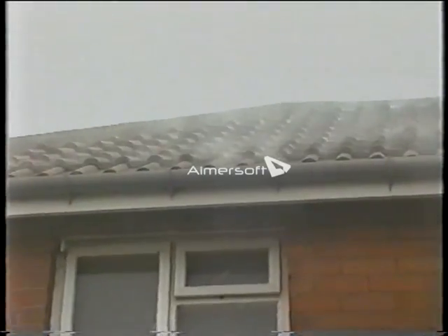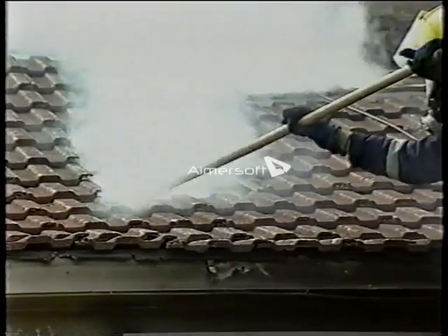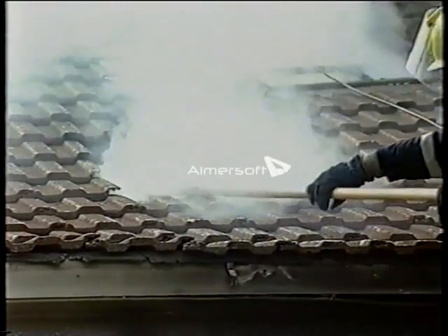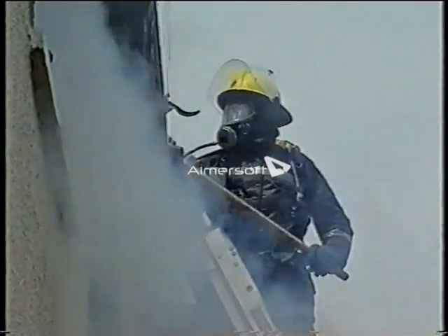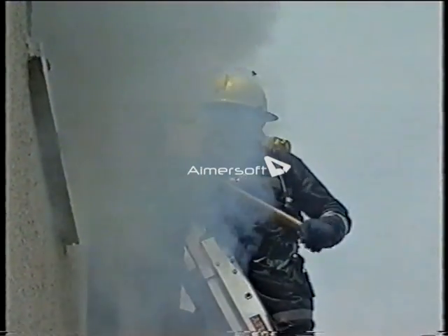When vertical ventilation, making a hole in a roof, is chosen by the officer in charge, careful consideration should be given to the safety of firefighters, both above and below, due to the possibility of structural failure. Timbers may be fire weakened, and at 600 degrees centigrade, even steel has only 1/3 of its normal strength. Firefighters should always position themselves at a lower level than the opening they are making, to minimize any risk of injury.